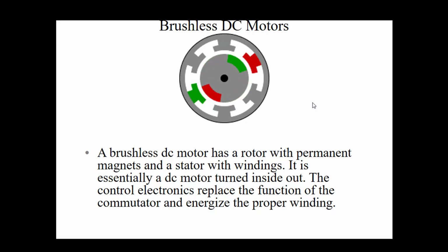It was switching of DC, and here it is also switching of DC, but the DC is switched in such a way that it produces a three phase alternating current, and we are ensuring a flow of three phase alternating current through our machine winding.